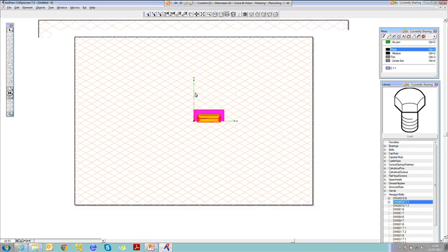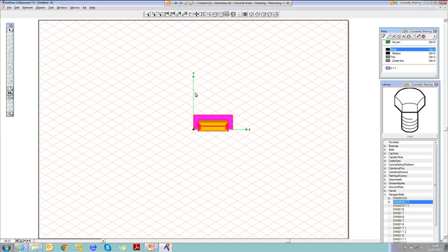So you can see that the more components in the assembly, obviously the larger the assembly file, the longer IsoDraw will take to import it, because there's a lot of information it has to interpret. But even this quite substantial file is quite happy to import. And you could then select it, place it in your isometric view, and move it relative to the X, Y, or Z component. You might then pick a component and move it out.